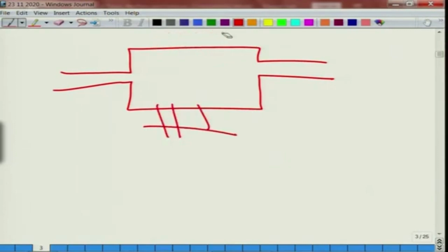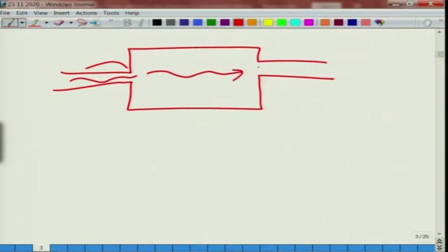So, basically the structural vibration noise is prevented, and all the structure does is, when the wave arrives here, a lot of it is reflected back and some part is propagating downstream. Again it meets an area discontinuity, again some part is reflected back, some part is transmitted, and some kind of a standing wave pattern is formed here. So, apart from introducing inlet and outlet ports of diameter much smaller than the chamber or the shell diameter, there is nothing much to it. So, that is why it is as simple as it can get.